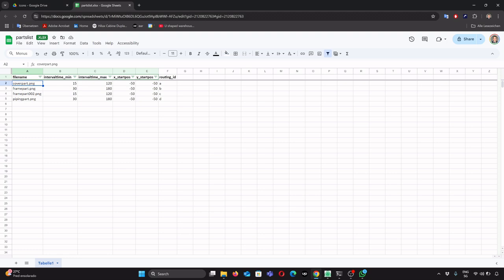The simulation runs with a randomly distributed job interval time per part, and then it creates instances of those parts representing jobs. So by adjusting the min and max values, we influence the distribution of interval times of jobs generated for this part.